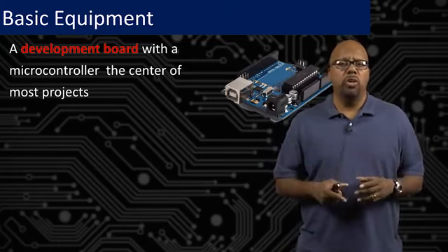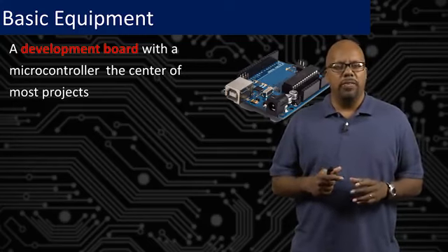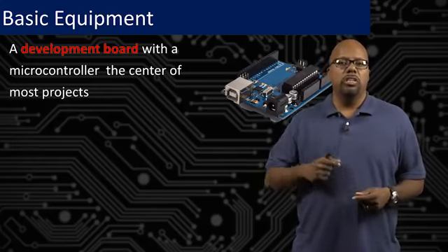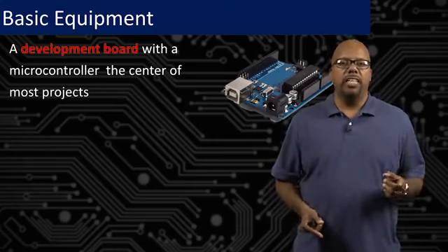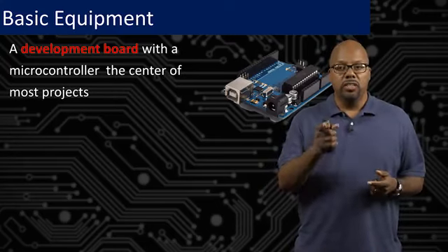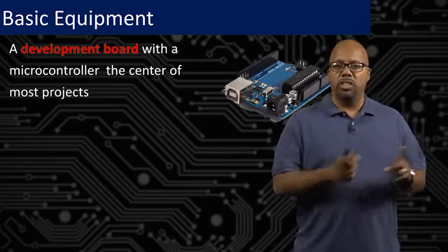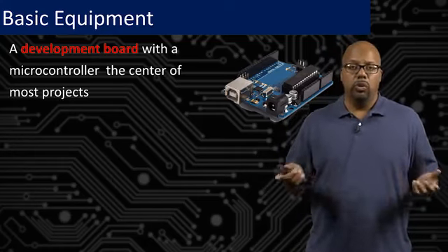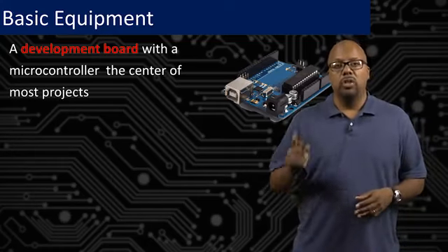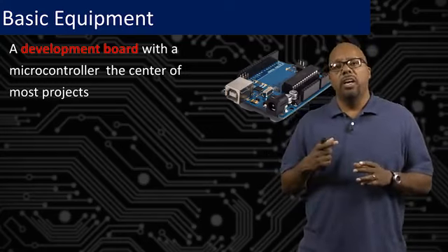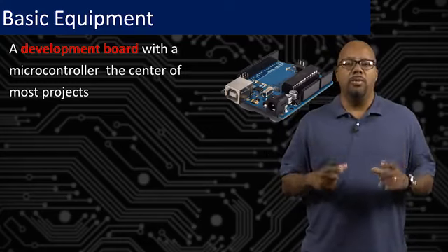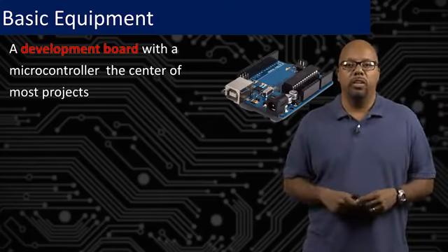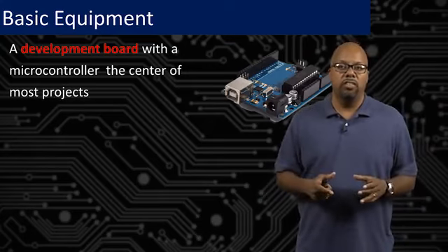Generally, the main thing those development boards have to have is a microcontroller that you're going to program, but also hardware on the board to program the microcontroller. Basically, data has to get taken from the USB cable, which is connected to your host, and programmed into the flash memory of the microcontroller when you want to put a program onto it. So typically, these boards will minimally have hardware whose job it is to read the USB cable and take the data received and program it onto the microcontroller. That's a minimum thing you're going to find on these development boards.